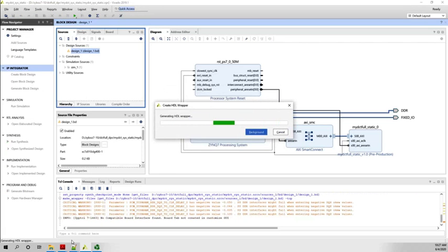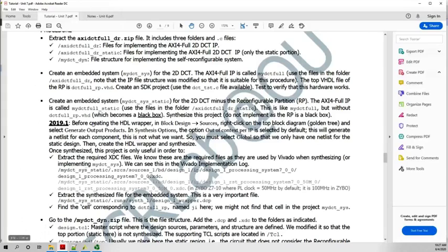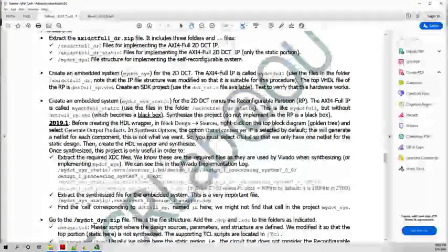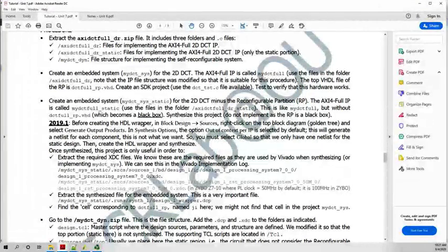Okay. So now, why did we do that? If you remember, well, because by default, when you synthesize this thing, it will create one particular module. It will create a synthesized circuit for one particular module. But this is not what we want. What we want is a synthesized circuit for the entire system. And this is a global option right here. Okay. By the way, we did this before already.